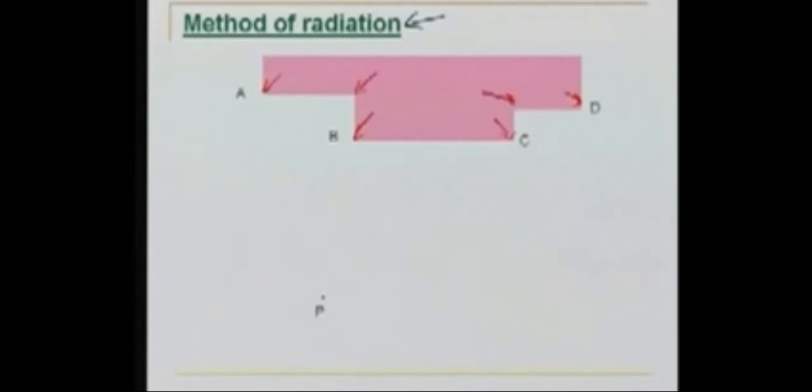What we do is occupy a point on the ground, which is P. This point P is where we are keeping our plane table. In order to plot this big building, this big building has to be accommodated in my sheet.